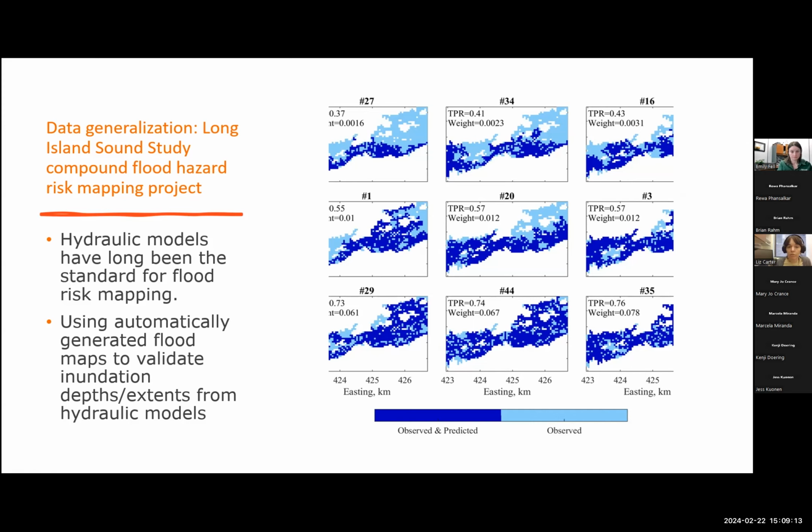So, currently, if you want to evaluate flood risk, riverine, coastal, or fluvial flood risk, you're probably using a hydraulic model. You're probably using a kind of physics-based model that is predicting where water is flowing along the landscape based on elevation gradient, the energy profile of the water itself. And the modeling frameworks that we're using to predict flood risk have been around for a very long time. And we, up until recently, have never really had data available to validate how well they're working at predicting the spatial distribution of flood risk.